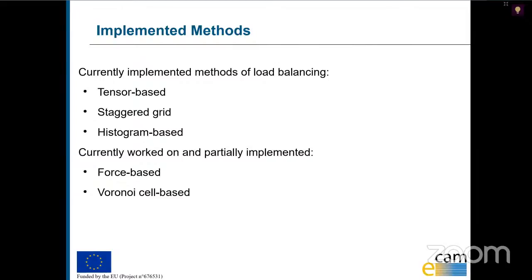The force-based version basically pulls the vertices of the domains into the direction of the most work, and the Voronoi cell-based method does something similar, but is based on the idea that you move around the Voronoi creation points in the direction of the work distribution.